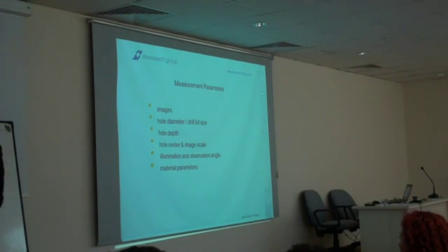Because with strain gauges, sometimes it's a problem. What I remember from making measurements at university is that sometimes you make a hole a little bit too close to a strain gauge, which gives quite a lot of error in your results. You don't get so much strain in these two strain gauges, but you get much more here, and it's a big effect on your results.